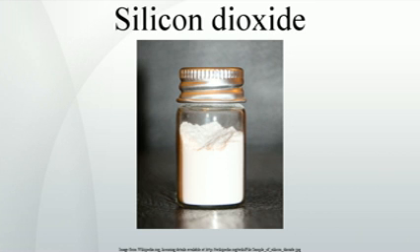The depth of the layer of silicon replaced by the dioxide is 44% of the depth of the silicon dioxide layer produced. The native oxide layer can be beneficial in microelectronics, where it acts as an electric insulator with high chemical stability. In electrical applications, it can protect the silicon, store charge, block current, and even act as a controlled pathway to limit current flow.